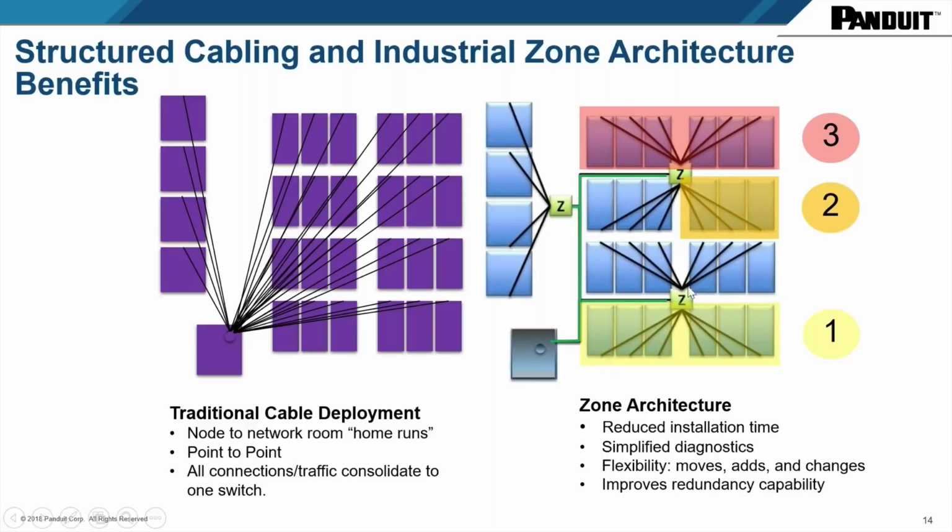So architecting a network and basically separating the zones into different zones will mean that from a central location to each one of those zone controllers, you are running fiber, and that depends on the distance, of course. And it's also running at a ceiling level. So therefore, you would need maybe a zone 1 or a level 1 MICE for this green cabling going to different zones because they happen to be running in a ceiling environment.